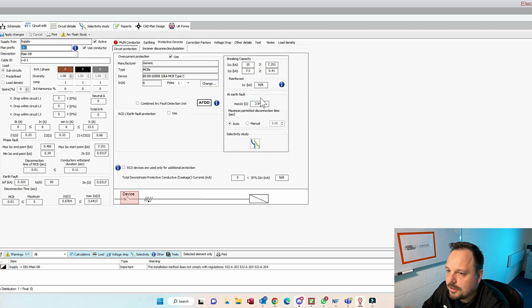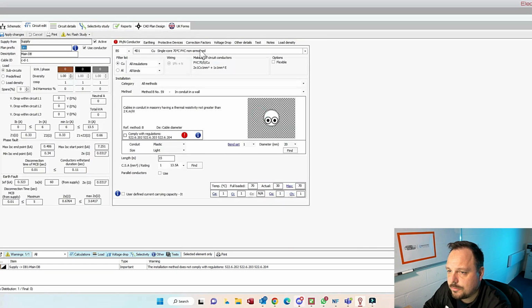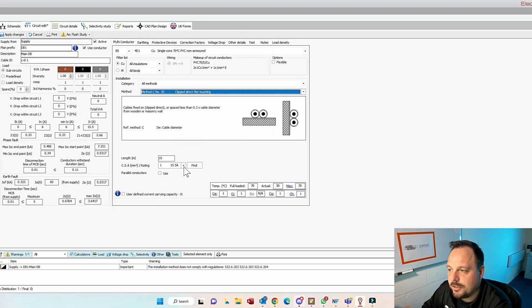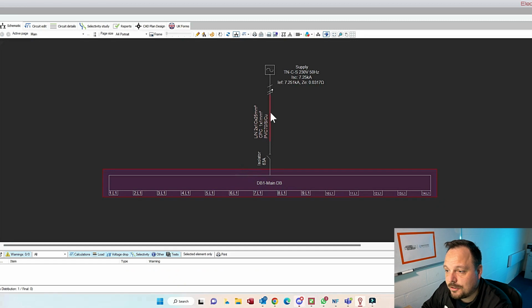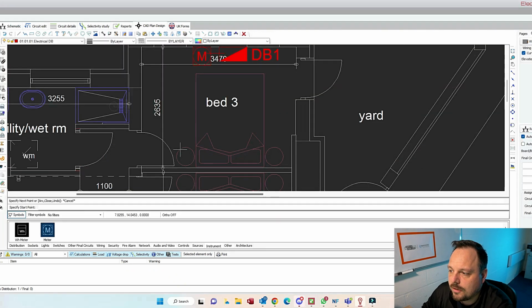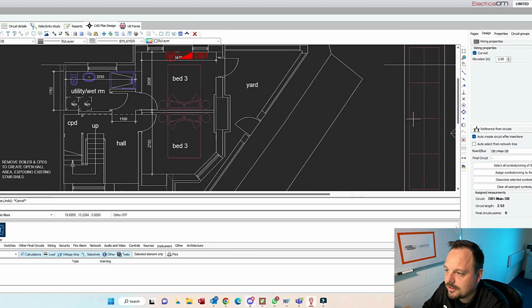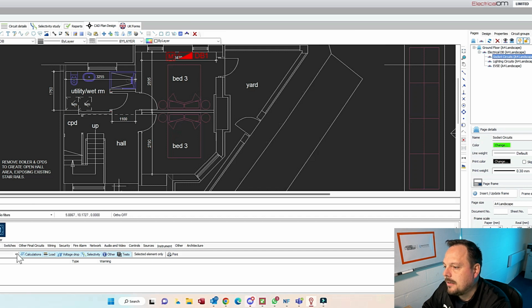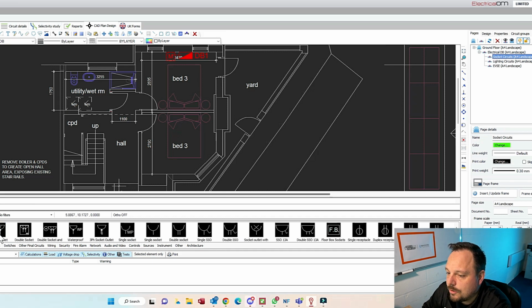If we jump across to the schematic, you can see it's understood that, and we're just going to make some changes to some of the defaults that pop up when you do make those connections. It does it if you're doing it in schematic mode or in CAD. You can adjust what they are, but I just need to make sure we've got that set right for what's going on the wall. So I'm changing the conductor sizes and getting rid of some of the isolators that aren't actually there.